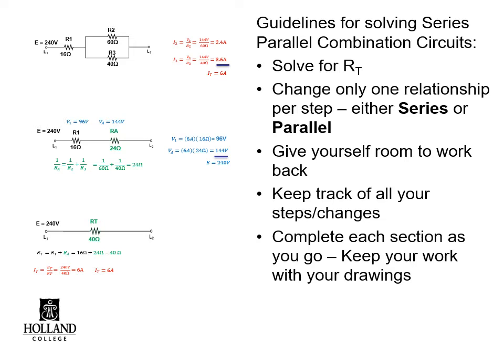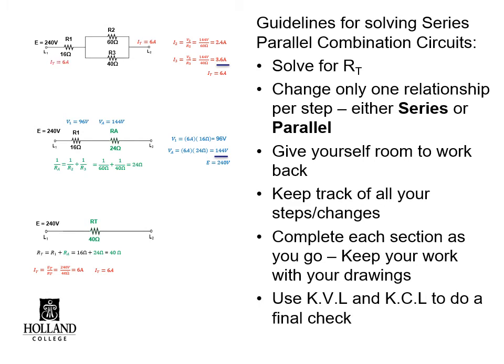So as you solve your way down to get your RT, calculate everything you need in the simplest form. That bottom circuit just had one voltage and one resistance, so it was easy to find one current. When you work back one step to row 2, the only thing you had to find there were the 2 voltages. You would then carry the voltages back up to step 1, at which point you had all the voltages, and all you had to do was find the 2 branch currents.